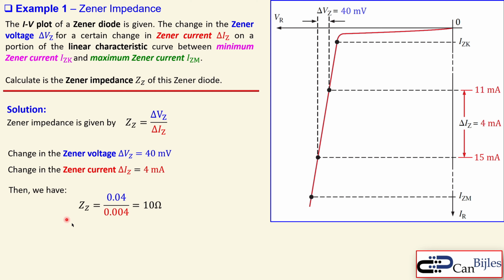By the way, this is a maximum. It can be that this is steeper or a different slope. In this case, by the way, it is less steep, so you will get more resistance. So that is important. You need to keep your line, your definition for the Zener impedance, in this part, for the operating and the regulation. So this 10 ohms, that's actually the answer for this example, looking at the graph. You can pick any graph from the datasheet and do the exact same.